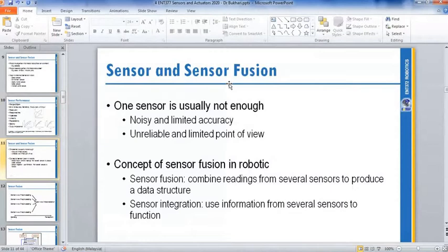If you use a laser, you cannot scan a mirror. With a vision system also, you cannot scan a mirror. You will have a confusion problem because you see more images in the mirror. When you use a laser sensor on a mirror, the laser will also fail because you have a reflection problem.